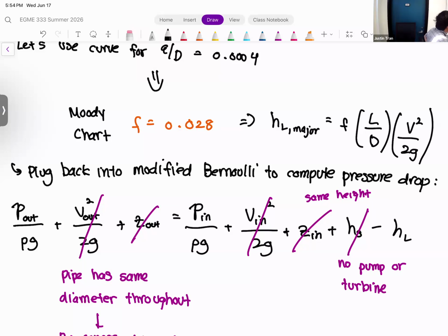And another part: instead of just going from 2-inch to 4-inch, is there any side effect of having a straight 4-inch all the way out? It's bigger flow, but it reduces the pressure and slows it down because it's a lot wider now. Because you're still going from four 1-inch to a 4-inch, right? Yeah, that would increase your minor losses too.